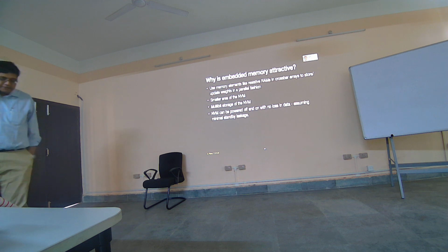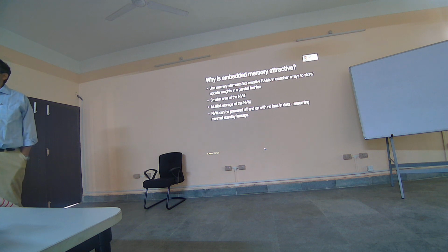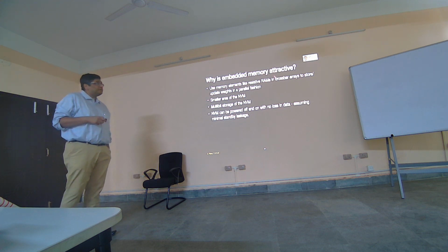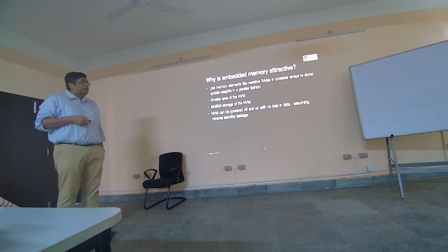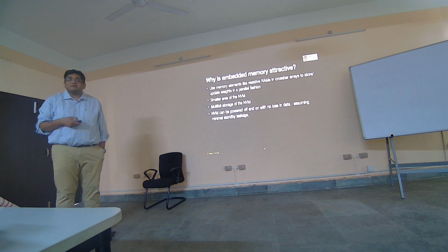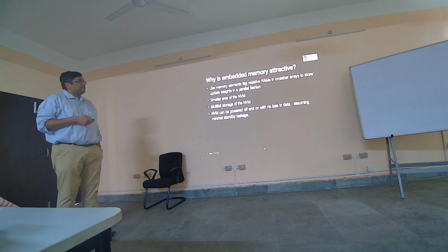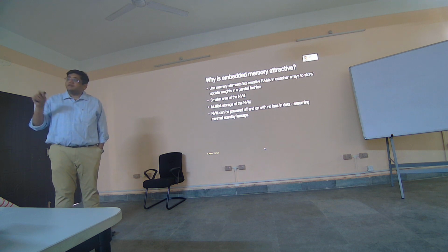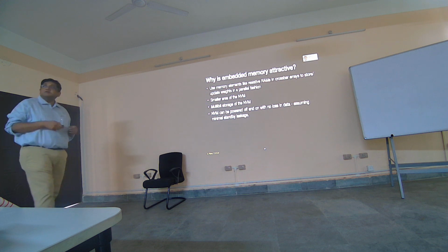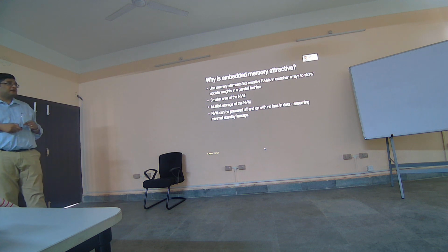Okay, so far we've discussed all these architectures. Now I want to understand why memory is important. What is it about memory that makes it so attractive to us? The first thing is memory elements like resistive RAMs. We'll talk about that in a bit. There are these special resistive RAMs which have a very elegant and easy method of updating resistors, and in addition, they have a much smaller area. If you want to implement an adder, it's going to take a large amount of area on the chip. Rather, if you implement that using a non-volatile memory, you'll see that the area is substantially less.